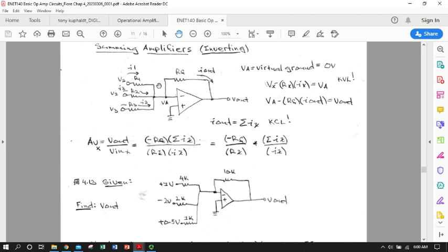Okay, so let's look from the Kirchhoff's voltage law standpoint. If we take any point here, V1, we've got an input voltage signal coming in. We have R1, selected by us or maybe a colleague who built the circuit. So we know that I1 is going to be V1 minus VA divided by R1. We can apply Ohm's law and relate this voltage to the input voltage and the resistor.